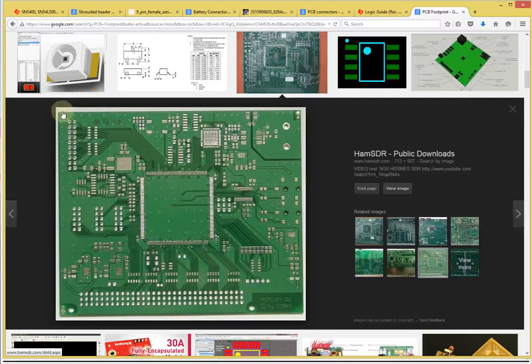So in the end, the construction of a physical board in your EDA software toolset is basically producing a board with a bunch of footprints aligned accordingly to design criteria, right? So you have a combination of through-hole footprints, that you actually have holes that go through the entire board, and then you have some of the footprints which are for surface mount parts which sit on top of the board. And there are a variety of those parts in various types and forms that you can place on your board.